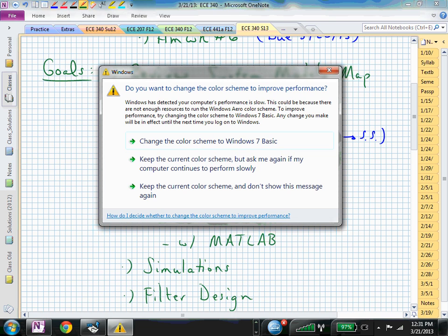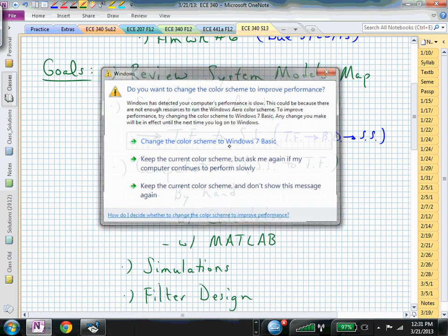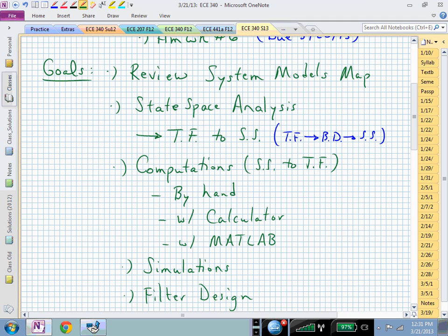In particular, after we look at that block diagram, just to get our bearings straight, I want to go one more direction and take a transfer function and create a state space representation from that transfer function. We really won't do that process directly. We'll do it in an intermediate step. We'll take the transfer function to a differential equation and then a block diagram and then a state space. So we're going to go quite a few steps between the transfer function and state space.